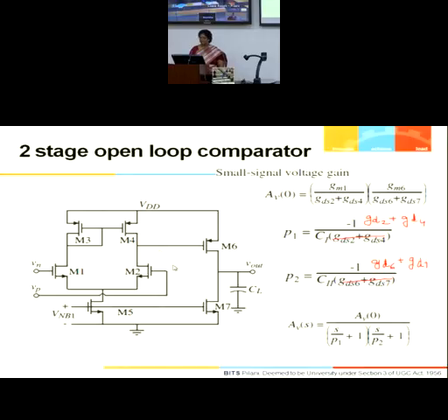In this situation, the charging will happen with I6 minus I7. And if I6 is much larger than I7, it's roughly equal to I6 by CL. The slew rate would be roughly equal to I6 by CL, in case I6 becomes so large that I7 is negligible in comparison.